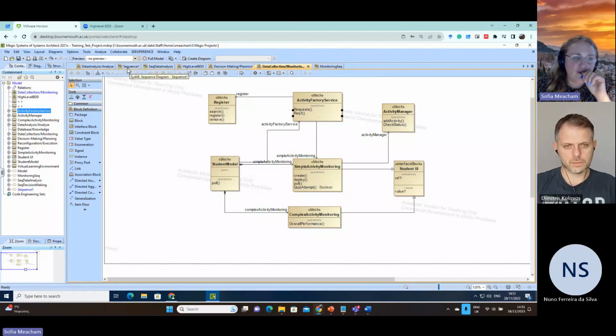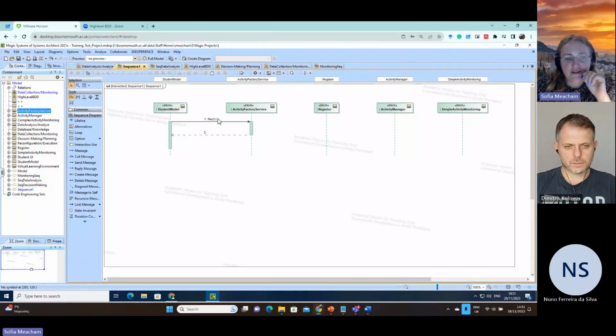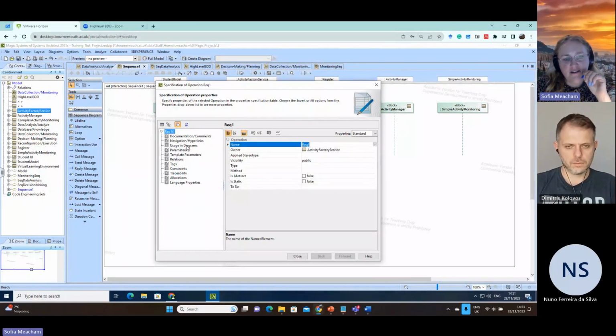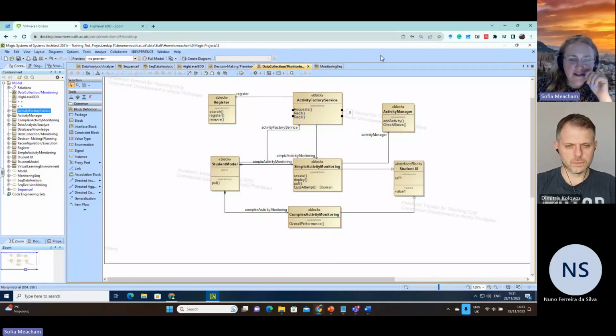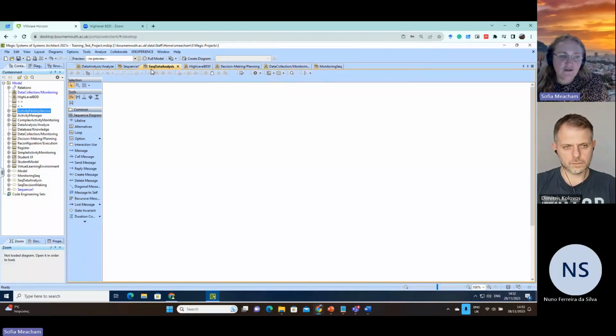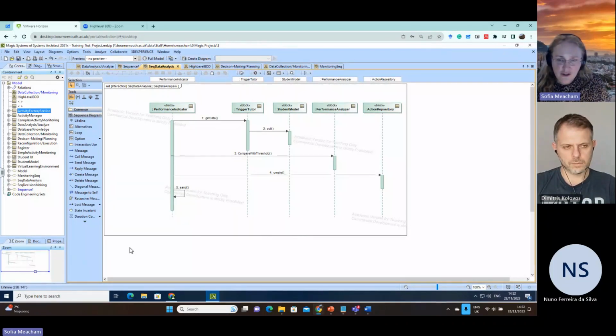So that way, you can be in your sequence diagram, create messages, use this clicking here and usage in diagrams, and then your block diagram is automatically being updated. Now I did it twice, so I have two requests. One, it automatically updates the information and what it should be there. There is another, not only the operation for the synchronous messages, for the asynchronous it is a signal. So likewise, when you have an asynchronous message, you go and you create automatically the signals in your sequence diagram. And it's one of the demonstrations of how the diagrams can be connected between them.